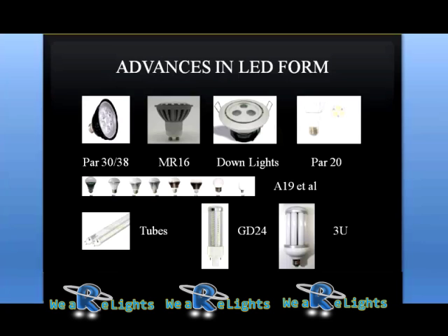The PAR lights are commonly called spotlights. PAR stands for Parabolic Aluminized Reflector. And you can now forget that fact since nobody will ever ask you about it again. The number after the PAR stands for 1/8 inch increments. So a PAR 30 is a total of 30 1/8 inch increments or 3.75 inches wide. And MR16 similarly is 16 1/8 inch increments or 2 inches. After you've seen a few PAR 38s and MR16s, PAR 20s and 30s, you'll start recognizing them from their size alone.